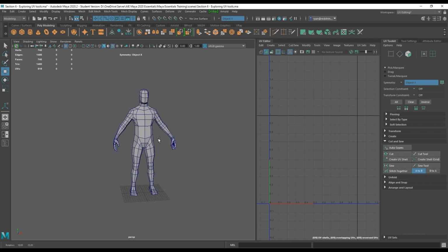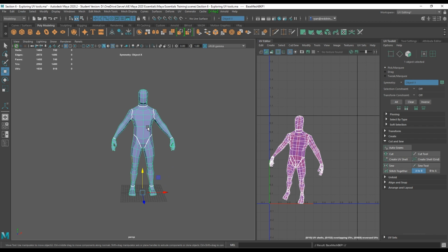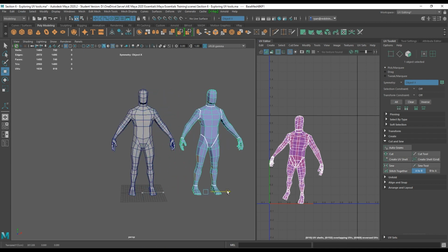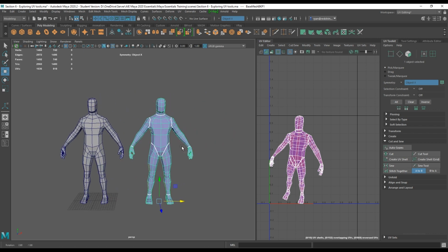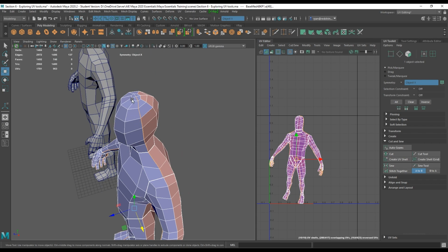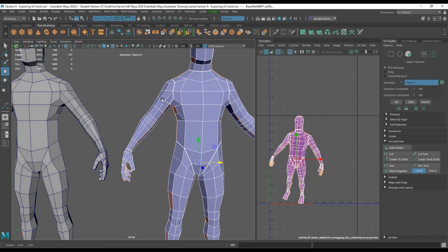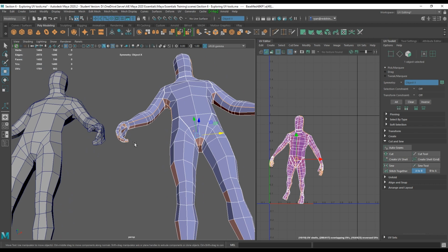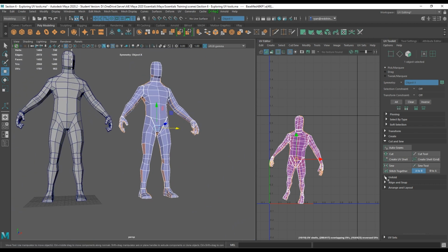So now we've played around with doing the manual cuts. If I grab this guy and Control D to duplicate it and move it across, you'll see they've got the same UVs because it's the same object. But let's try a tool from Maya, this automatic seam, and let's see what seam lines Maya would think would have been better. So I'm selecting the object, clicking auto seam. Maya does the math, and now we can look through here. See, it's added a seam line going through the top of the head here, and then basically through the fingers here. And let's see, for interest's sake, if we go to unfold, how this would unfold.